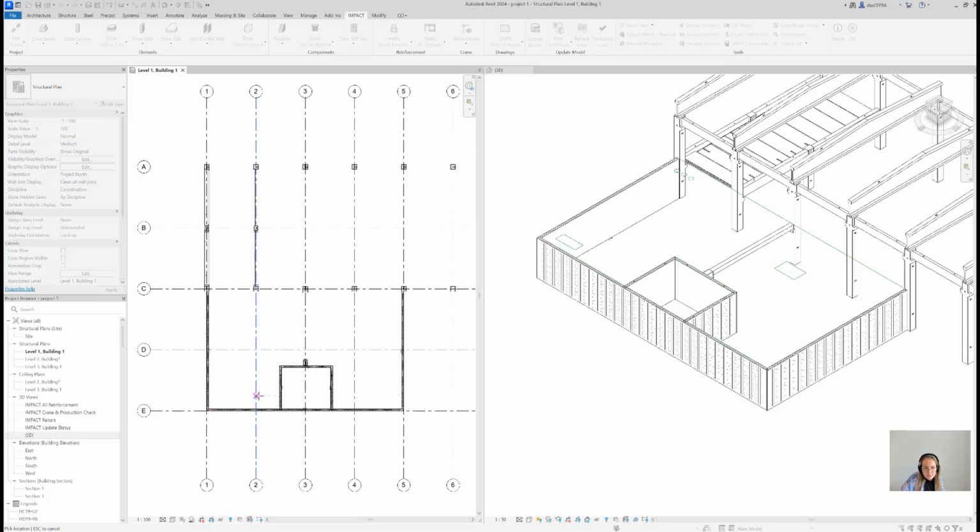But now I can see something is happening, and it says pick location, and I'm going to pick those three reference lines. It actually doesn't matter if you click on the wall or just in here. Impact is just going to split on the axis, in this case must be the x-axis. Okay, so now we have selected the 3 points where we want to split. I press escape on my keyboard, and we agreed on a 10 millimeter gap.